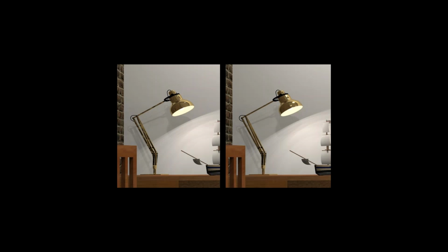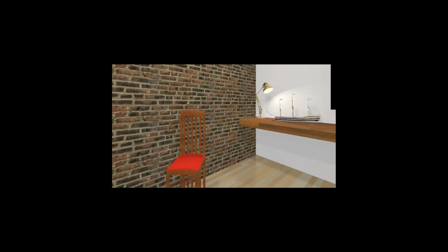Again, very important for you to understand that most of the time, selecting a preset is perfect for the rendering. But as the model builder, you have complete control over the finish to either lower values or bump them up to give you exactly the finish on the material that you're after. And our dialogues make it very easy to control the finishes.